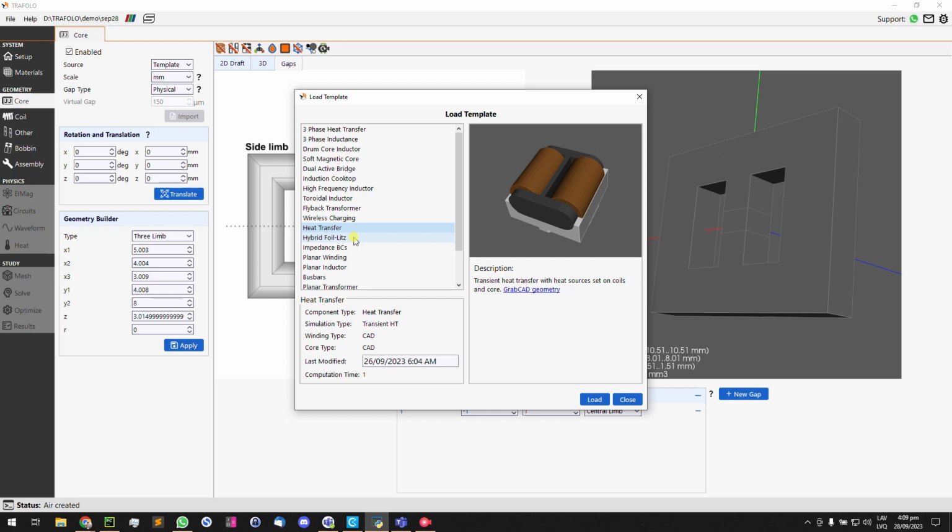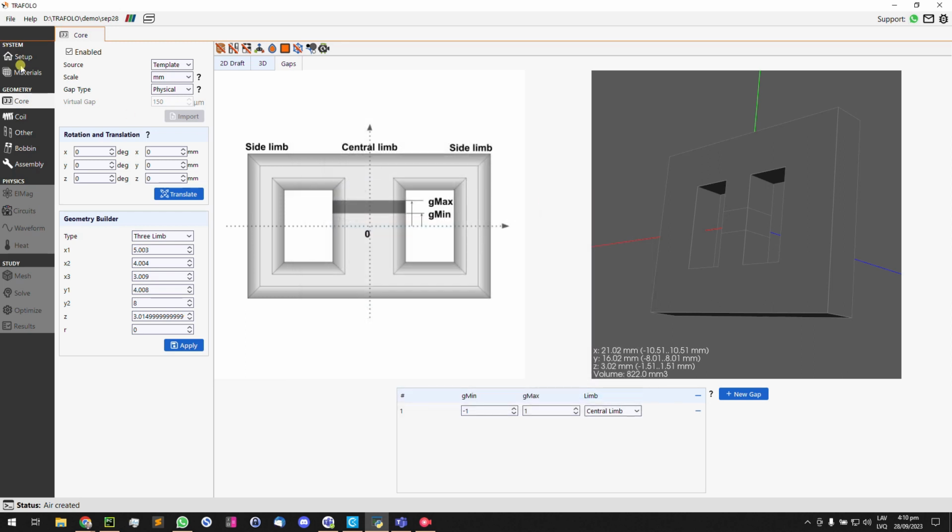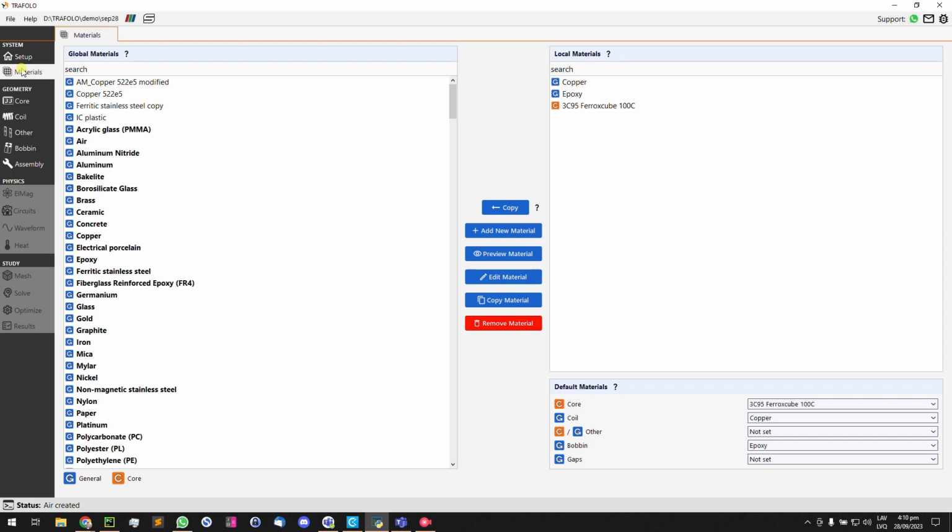So typically we set the gap as FR4, for example. So it has no permeability, but if you decide to make a core made of different, let's say, pieces, then I think yes, you can do it. But I will need to try it myself, as this is an interesting case. And the question also was about different material types: ferrite, nanocrystalline, amorphous, etc.